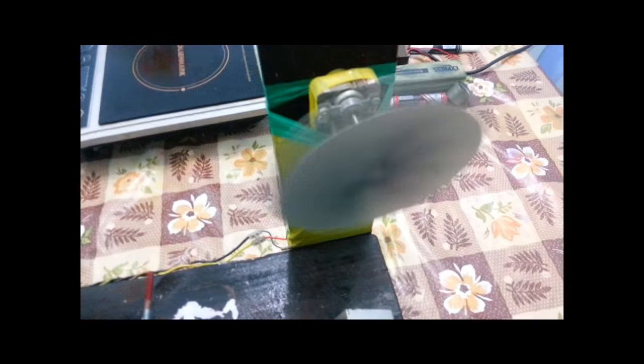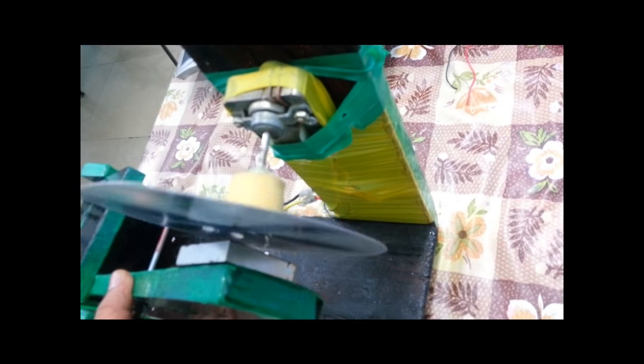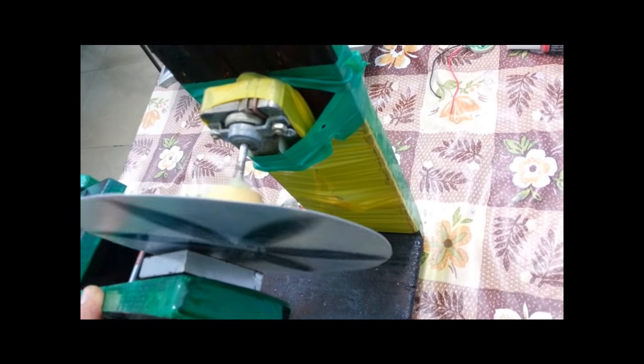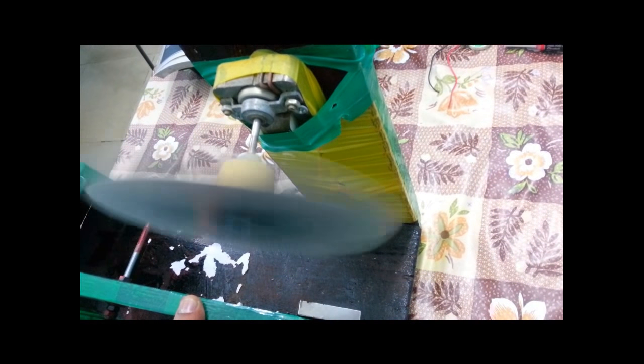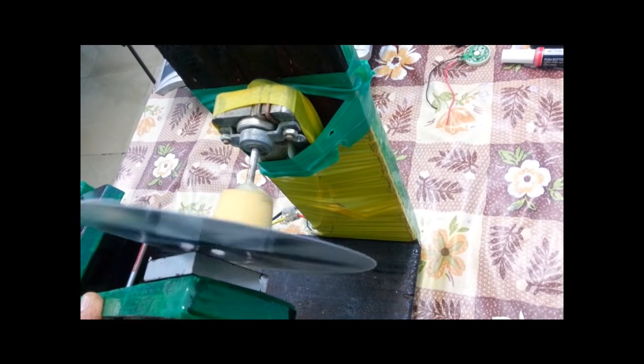Okay, when a current is passed through the motor, the aluminum drum rotates at a very high speed. And if I bring this magnet near the aluminum drum, you can see the speed of rotation gradually decreasing. Usually you know that aluminum will not be attracted by a magnet. But here the force is due to the eddy current. When the magnet is kept very close to the aluminum disc, it induces eddy current in it, and due to that eddy current, it experiences a torque in the direction opposite to the rotation, and it tries to stop the aluminum disc. If I remove the magnet, the speed increases again. If I bring it closer, it will reduce the speed. So we can even stop the rotation of the disc by adjusting the strength of the magnet.